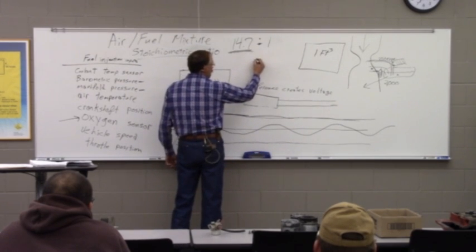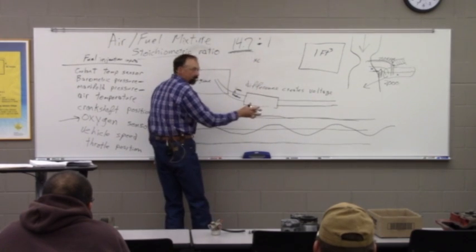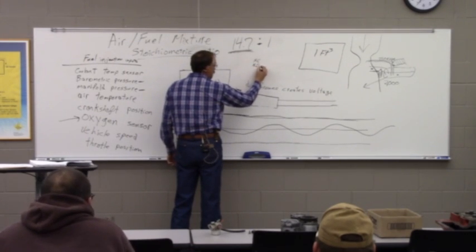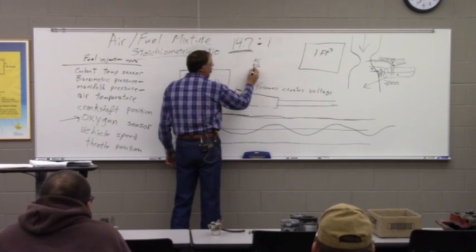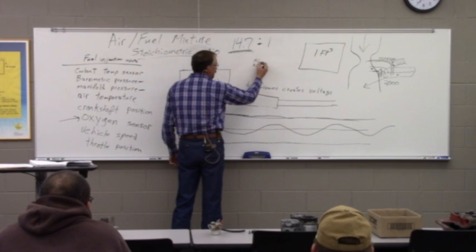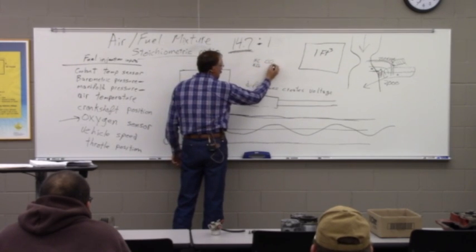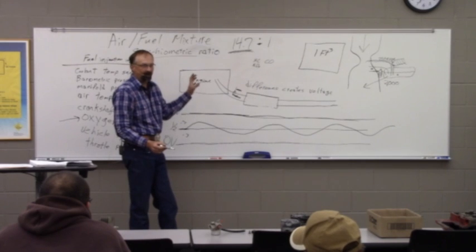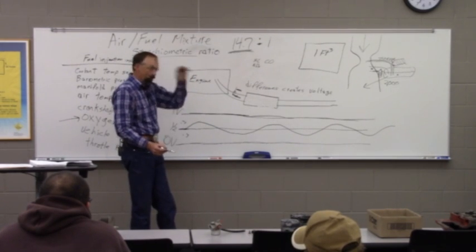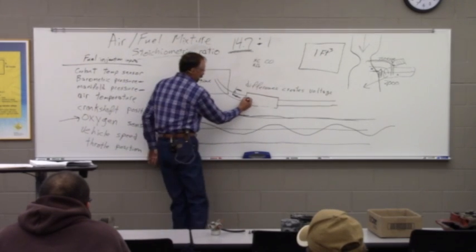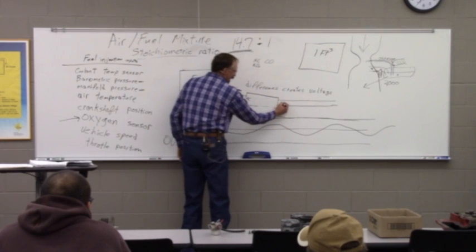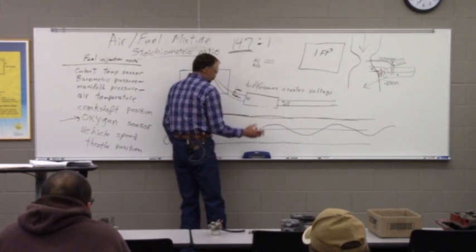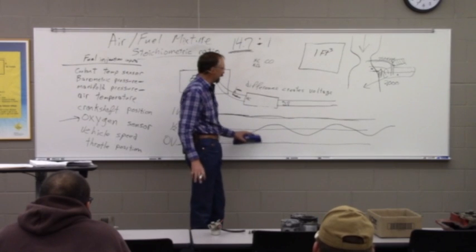It'll take our hydrocarbons that went through the engine without getting burned, and it'll also take our NOx, and they're only partially successful at controlling the NOx, but on the hydrocarbons and also on the carbon monoxide, this catalytic converter is really pretty successful at taking that stuff and finishing the reaction we wanted to begin with, so that when we have those things coming in this end of it, we've got our H2O and CO2 coming out here. That's a little side note on catalytic converters and what they actually do.